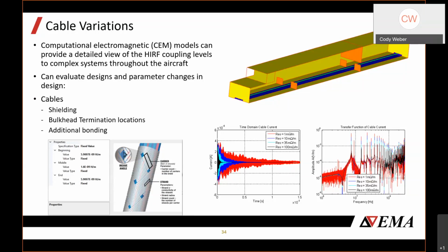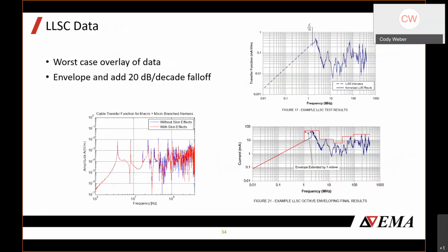And with those details associated with the cable harnesses, there's really a lot of the transfer impedance details that can be implemented with our tools. You can use it in terms of a specification where you enter the parameters directly, or we have an algorithm that can calculate, based on the carriers and the strands and the weave angle associated with your braids, what that transfer impedance might be, if you have no idea and there are no transfer impedance measurements available.